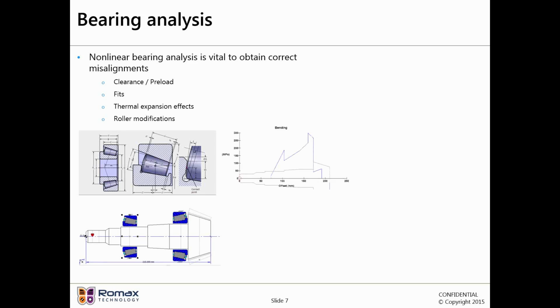And when Romax does the static analysis for shafts, it constructs the shear force, bending moment, and then stress diagrams, as you would from textbooks, but it's doing this including the bearing nonlinear stiffness, and simultaneously solving with the stiffness matrices and the gear load.